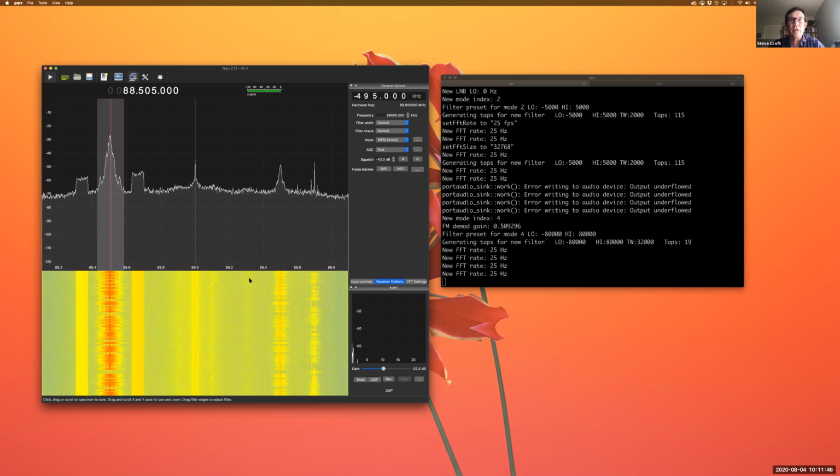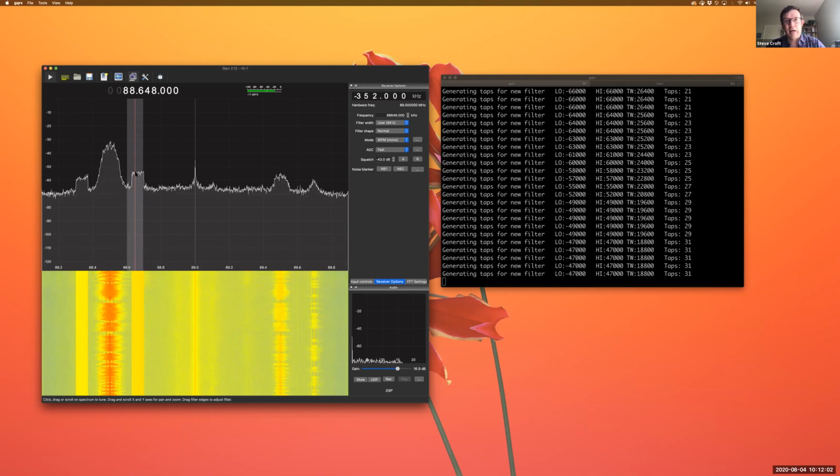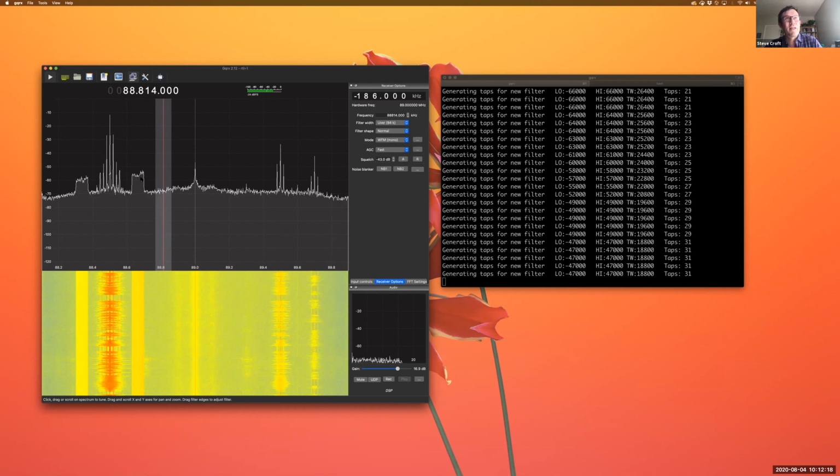So if I turn the gain up here again, I'm using this FM decoder right now, but if I scroll this over to the digital signal, it just sounds like noise when I'm decoding it with an FM decoder. It's the wrong decoder to use to demodulate this, right? I actually need to be able to unpack the digital information in here to get that signal back out. But it's also an example: you hear noise here, and you hear noise here, a little bit louder on this signal than here. And again, I come back onto the FM signal and I can understand this.